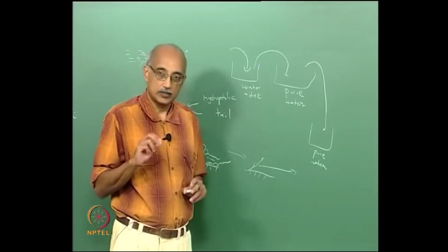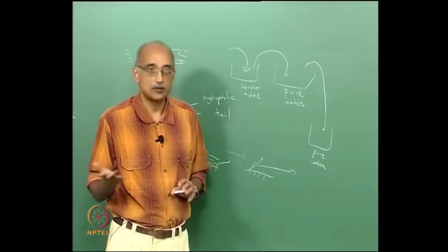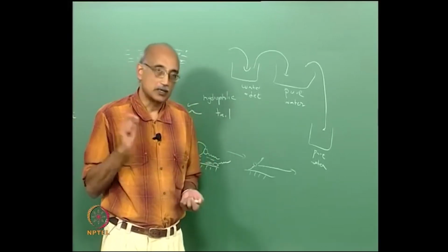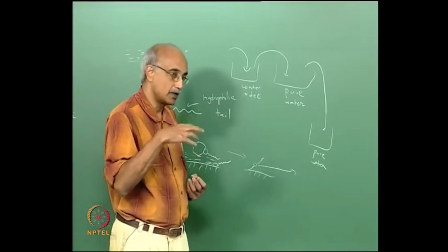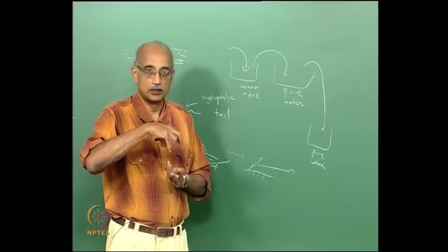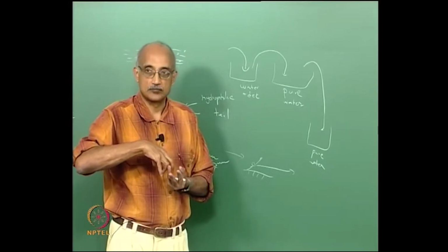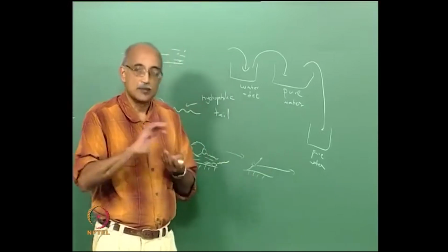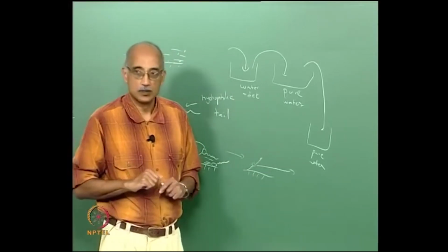Unless you are doing the cleaning with a high vapor pressure solvent, high volatility solvent, which will naturally evaporate. But even in that case, you need at least some kind of a vacuum to suck out the last monolayer of this high volatility solvent, because many of these processes you cannot even tolerate an atomic layer of impurities, leftover solvent for example.